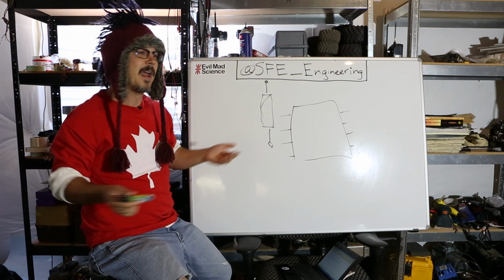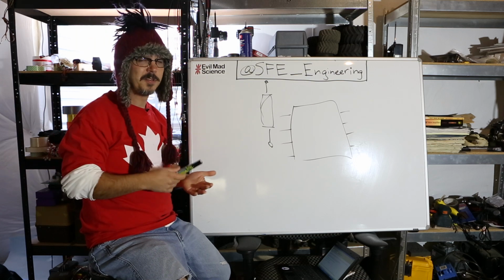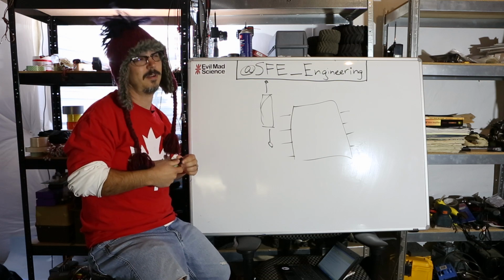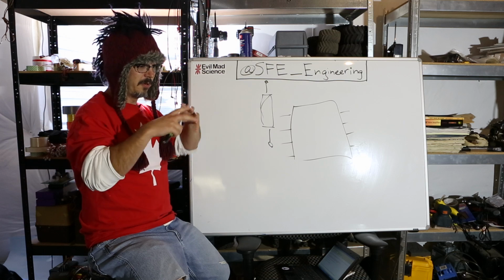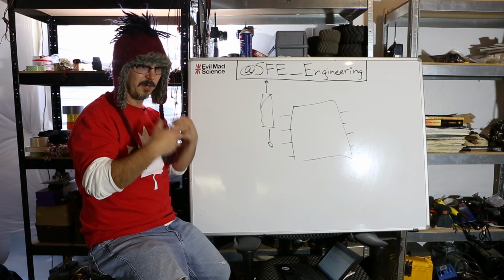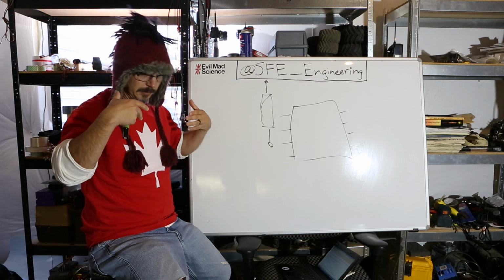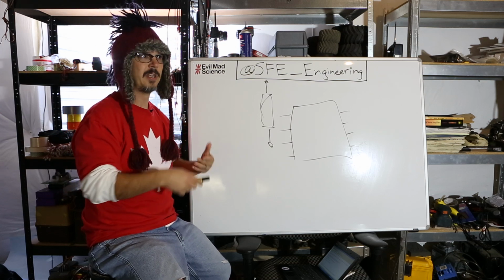There's no getting around that. But that's not the end of the world. Remember that I also said that the success of your circuit design is, to a very large degree, probabilistic, okay? So the shorter and more compact your circuit design, the shorter your traces, the more likely it's all going to work as intended initially in the end.